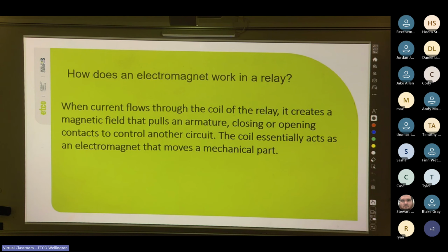So with relays, you're normally switching lower currents, generally up to maybe 10 amps. It's more like a two-position light switch. So you've got your common, your 1, and your 2. It switches the common between 1 and 2, whereas your contactor, which controls bigger current, is normally a closing.